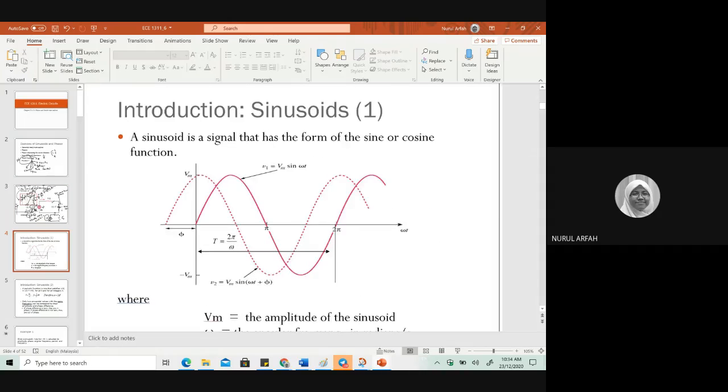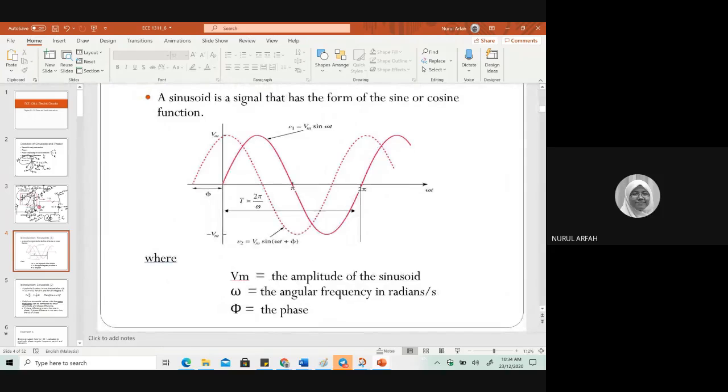All right. Do you have any questions? In summary, for this sinusoidal form, you will have cosine and sine, but usually you're going to use cosine to solve your question. And what is Vm? Vm is the amplitude. What is omega? It is the angular frequency, which is equal to 2 pi f. And then what is theta? Theta is the phase. The phase is basically starting from 0 right here. If you have it on this side, you have a negative, and this side will have a positive. So later on, maybe we go through one example, then you will understand this better.